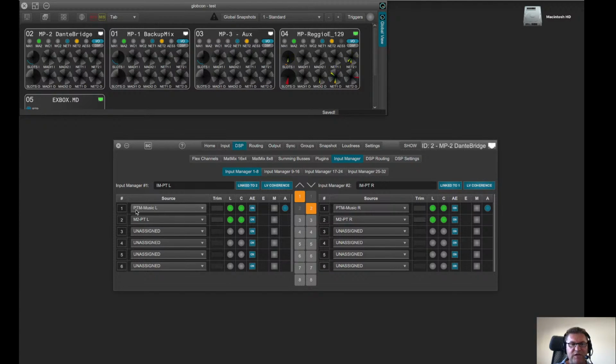So, if I'm having a failure on the Pro Tools on the Dante side for any reason, we will see that over the years. But if I still have the same signal on a MADI version from the twin device, then I can be sure that either one is valid, and therefore I can route towards the rest of my processing, which can be a Dante feed output or a MADI feed output or an analog feed output, the result of the operation of the input manager. And this is not just based on the locking availability of the several signals, an AES carrier, a MADI carrier. Of course, if you don't have MADI information, it means that there's no audio at all.